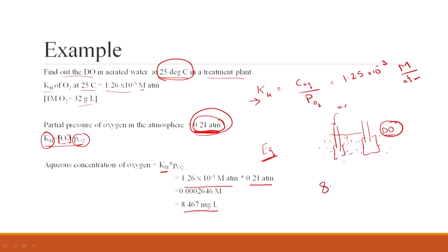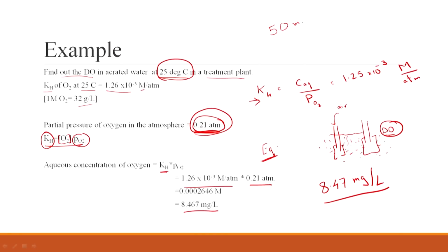We looked at the case of dissolved oxygen when we were looking at acetic acid being discharged from a treatment plant at 50 milligram per liter concentration, and I think the flow rate was 500 meter cube per day. You figured out how much oxygen was required to oxidize this acetic acid, and I think you got 2.6 kgs per day or something like that.